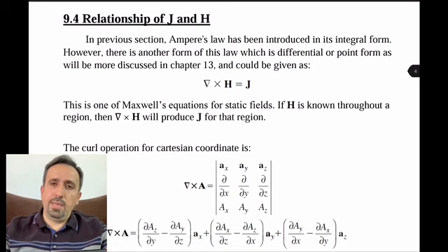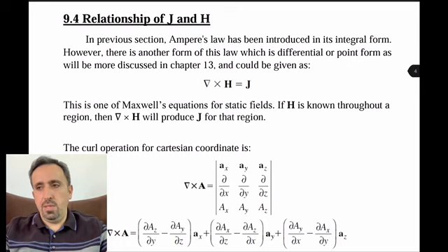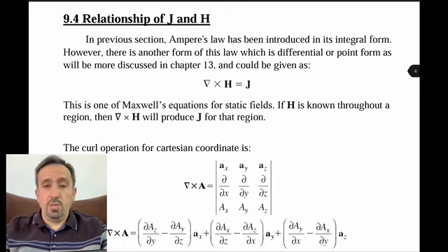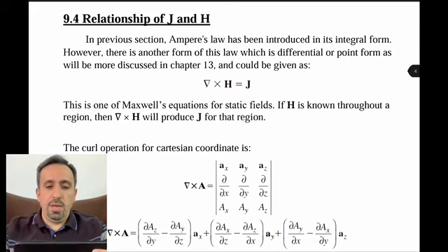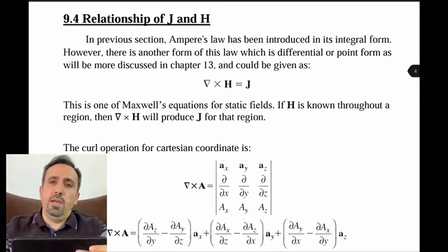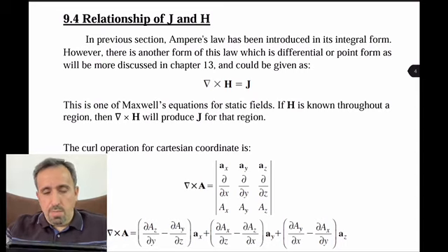It's unlike the previous example where we were talking about K. K is current sheet density, while J is current density. So current sheet density is the current per unit meter, while this is the current density for surface area, for example.